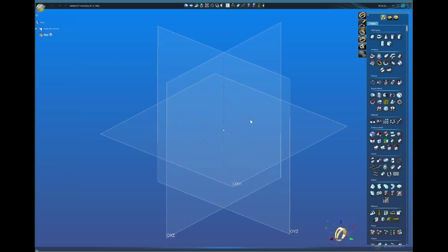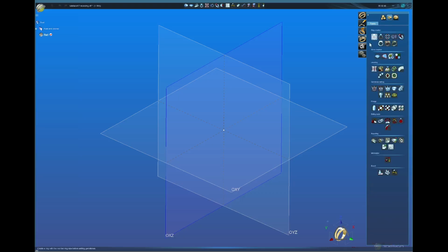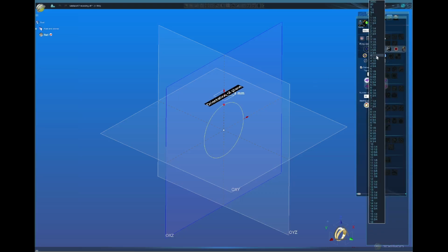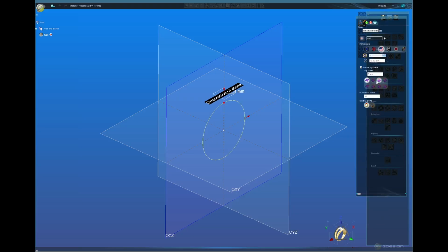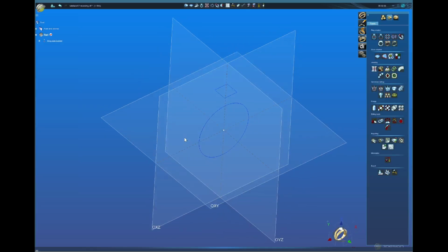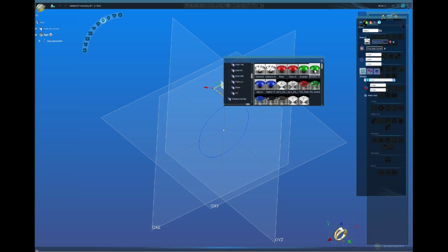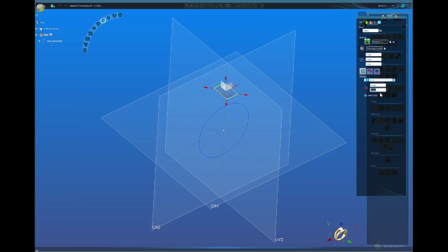So let's dive in. For this ring, we're gonna use size 8 on this plane. We're gonna bring sizing and we're gonna do size 8 and top plane 5.5 millimeters. We click OK. On the sizing builder, we're gonna bring an oval emerald. We're gonna do precious stones, emerald, and we're going to do 10 millimeters by 6.67. It's there for us. We click OK.